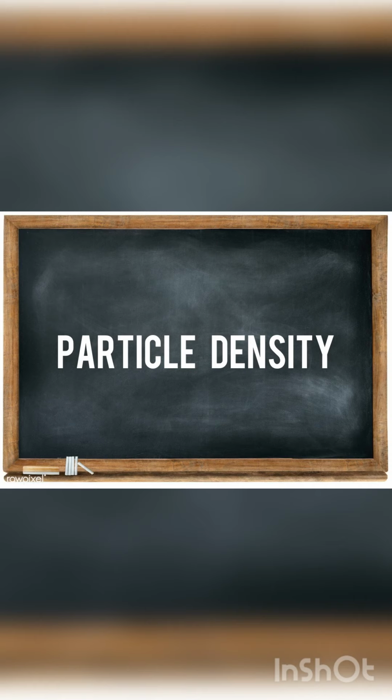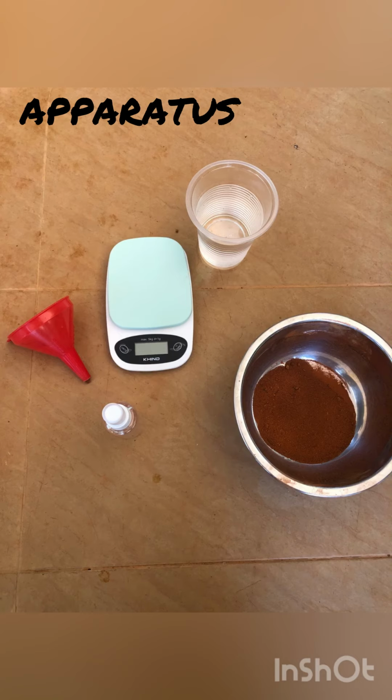Next, we move to the particle density test. The objective of the particle density test is to determine the specific gravity of soil using a density bottle. The apparatus of this test: first is a spray bottle as a density bottle, a funnel, water, fine grained soil, and then a balance.